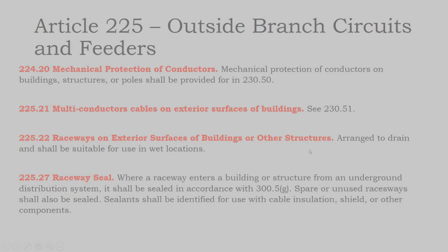Where a raceway enters a building or structure from underground, it should be sealed. Spare or unused raceways should be sealed. Sealants should be identified for use, so you have to use listed sealants. You can buy these things at your local hardware store.